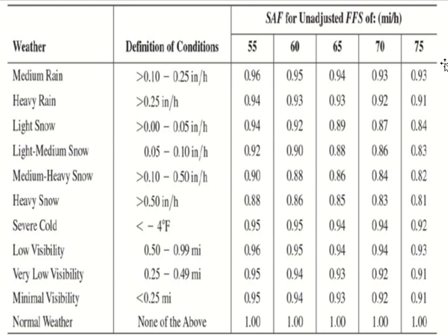Okay, it is less. So I will just take the last value. Okay, I just take 0.96. Clear? If it is between two values, I can interpolate, no problem. But it is even less than the minimum, so I will just take the minimum. Okay, 0.96. So SAF is 0.96. So free flow speed how much?